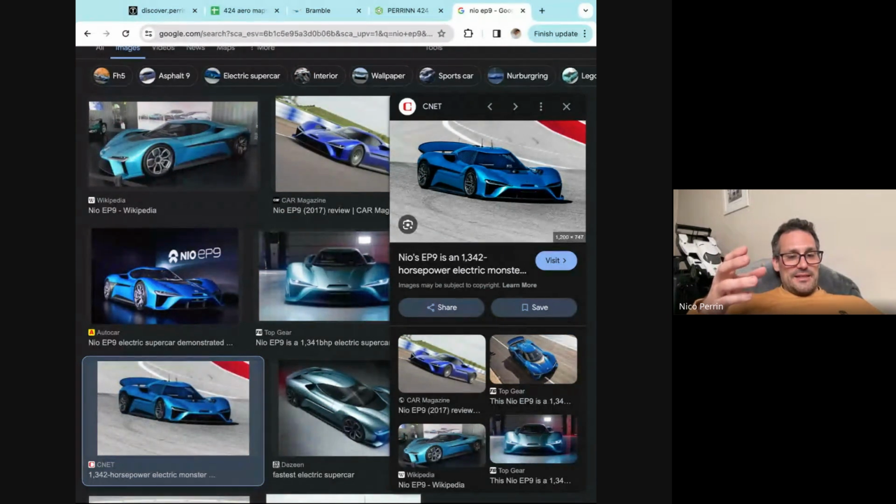If we're outside the 5% margin on downforce measured, then we might go to a full-size wind tunnel or even a more controlled environment. TotalSim has got a tunnel where you can test the real car inside, as in driving in a tunnel at speeds. Or you go to a full-size wind tunnel and then you start measuring in a more precise way and look at the flow on the surface and understand where it doesn't work. But that will be the strategy.